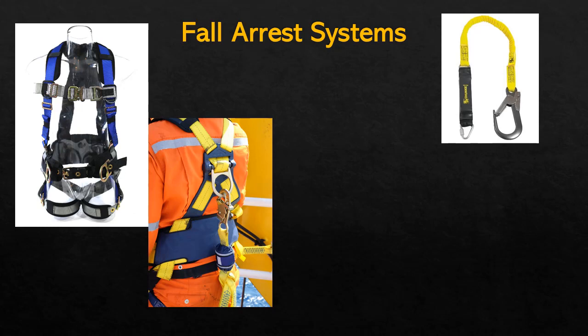Or sometimes it has dual hooks, but the hooks on a lanyard need to be routinely inspected to make sure that they don't come out of place, because if they do, there's a potential that people could slip out of them. What you see here with the lanyard as well is that once it gets force loaded, it will elongate significantly, and when that happens, it can't be used again. Basically, all the components of a fall arrest system, other than the anchorage point, are designed for single use only. Once they've absorbed the shock and saved the life of somebody from a fall hazard, they can't be reused at that point.